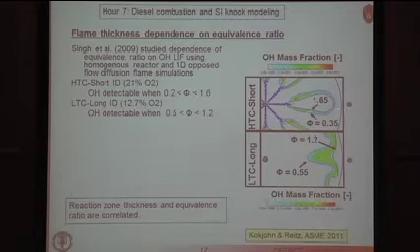And at the edge here of this OH mass fraction contour, we have this number. And then at the other edge, the lean side of the flame, where the equivalence ratio is low, we can bound that as well and read off what the OH would be. And what we find is that for this first case, where we have 21% oxygen or air, OH is detectable in regions where the equivalence ratio is between about 0.2 and 1.6.